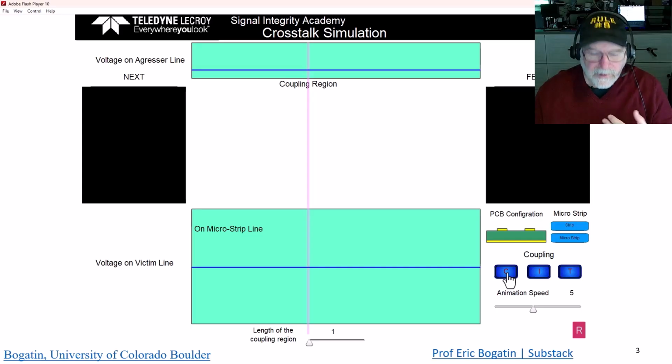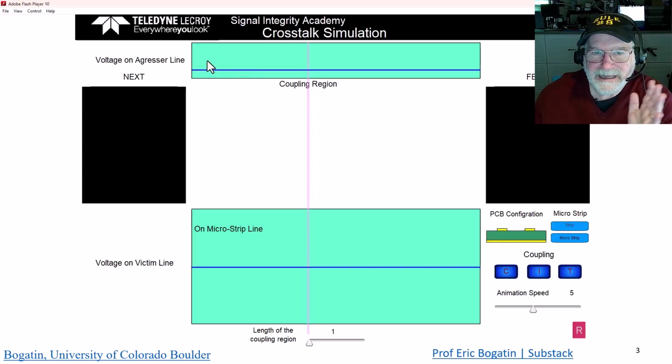And again, you want to apply rule number 9 when you do this analysis to think about what you expect to see. So let's see, we send a signal down here. Here's the edge, it's going to propagate this way. We only get crosstalk where we have the dV/dt or the dI/dt between the lines. That's where we have the edge.